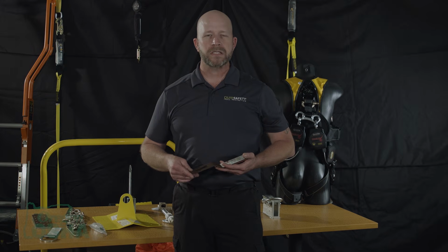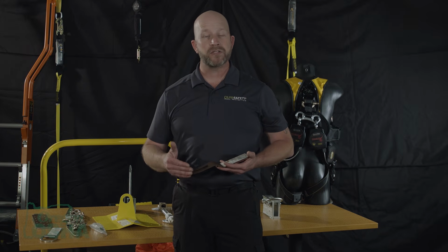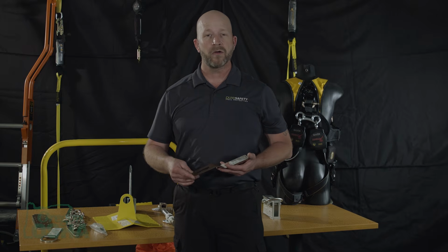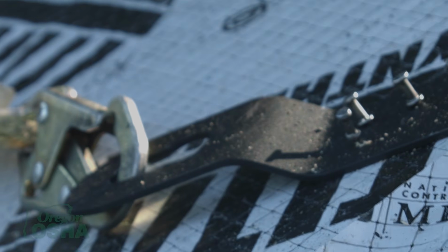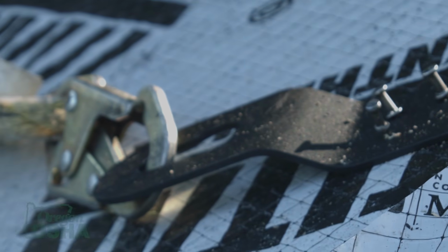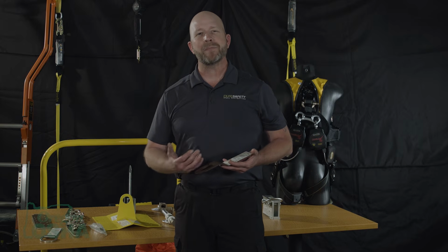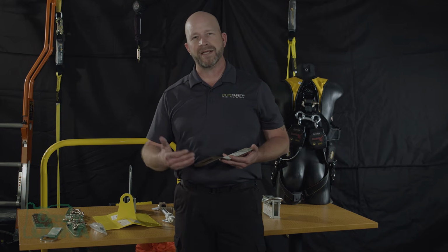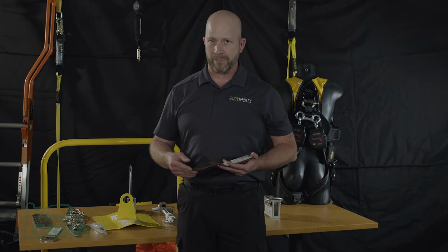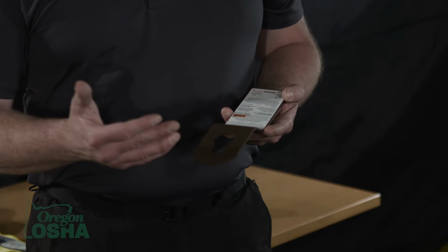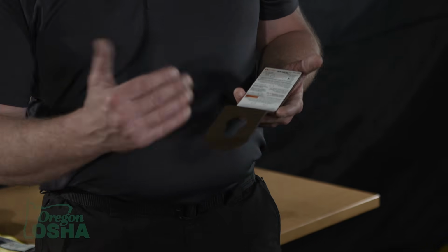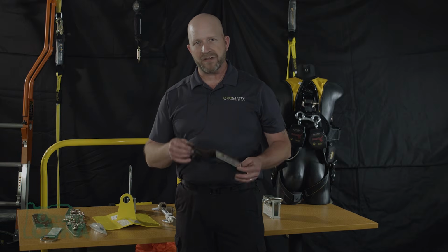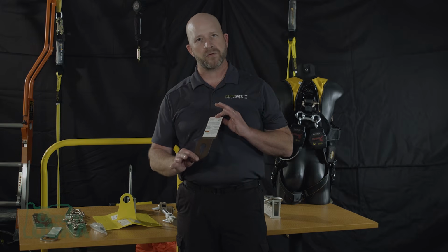In the OSHA requirements, it does mandate that anchorages used in fall arrest be designed with a 2-to-1 safety factor, or 2 times the intended load, or capable of sustaining a 5,000 pound load. Nothing says an anchor has to weigh 5,000 pounds, merely that it be capable of sustaining that load, plus a little extra because we don't want to fall, and then later on it breaks while we're hanging, waiting to be rescued. So the design and features of it is all about engineering and force principles, so anchors don't have to weigh a great deal. They can be even something as easy as a piece of extruded aluminum.